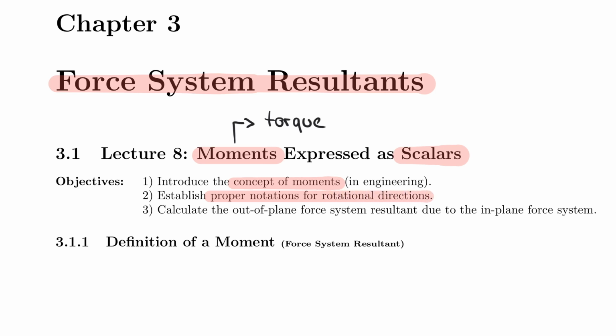And you will see that you will need a very solid understanding of a 3D coordinate system, because again, they are actually directed. And ultimately, we want to, of course, calculate the moments out of the plane of that force system. So we want to calculate the force system resultants, which are usually out of plane for in-plane force systems.